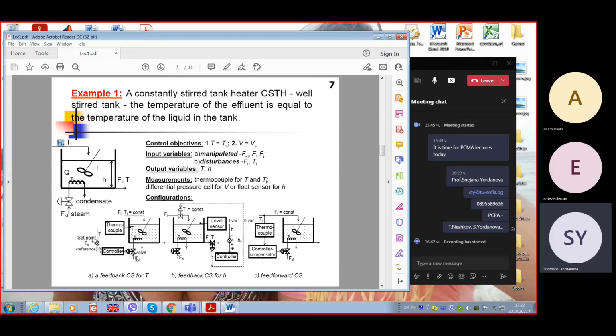So we do not measure flow rate, but we know the output of the controller, the voltage to this valve. So our plant has output the end of the thermocouple, because we cannot know the temperature unless we measure it, and input the output of the controller.